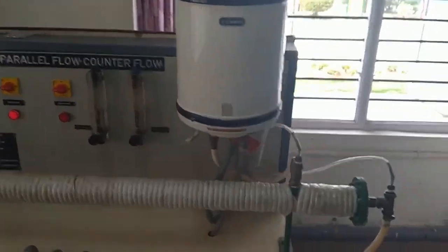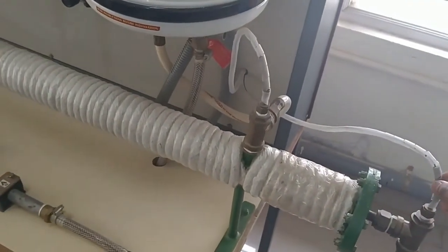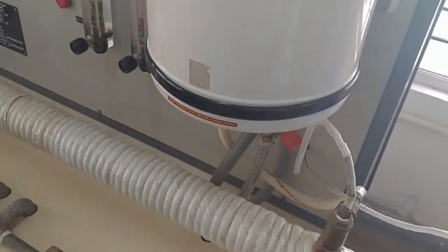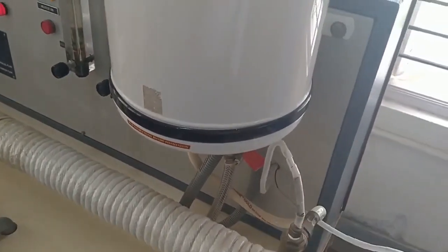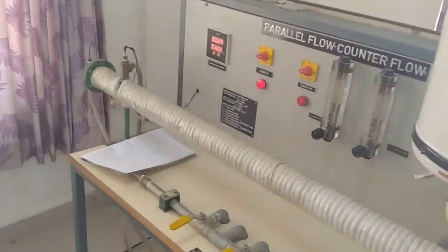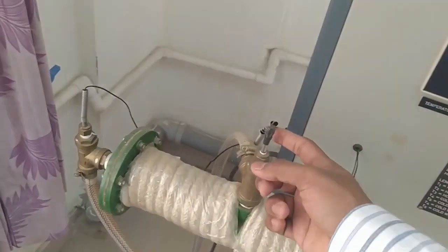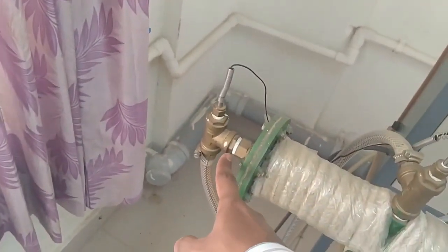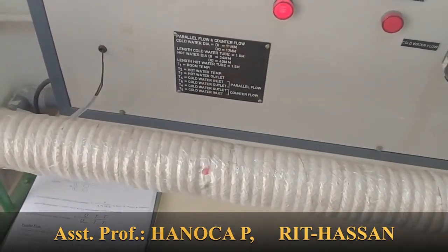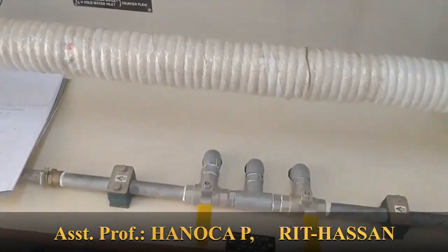Here we can see the cold water inlet section. This is the thermocouple to measure the cold water inlet temperature, and this is the hot water inlet section with its thermocouple. This is the geyser where we are getting the hot water. Here is the hot water outlet and its corresponding thermocouple, and this is the cold water outlet with its thermocouple. Outside, the pipe is completely insulated, so there is no heat transfer from the heat exchanger; heat transfer takes place only inside the heat exchanger.